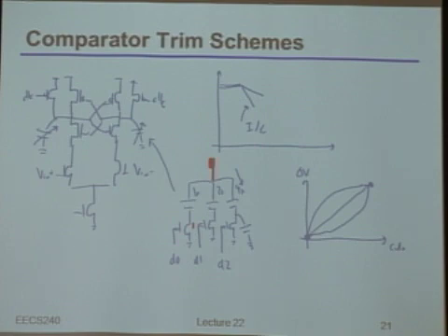Yes? So a couple things. First, wouldn't we want to actually operate in the top curve regime because the step size will be smallest? So you said, wouldn't we want to operate in this region right here if I had this kind of curve? Yes, absolutely. The only problem is your range is more restricted. So that's why I said that if you always fix the range you're covering, the best way to make the step sizes small is to make it a linear map. Because if you always fix that range, it should be clear that anything that's not perfectly straight has a region where the slope has to be higher than it would have been if it was straight. That's really all I'm saying.